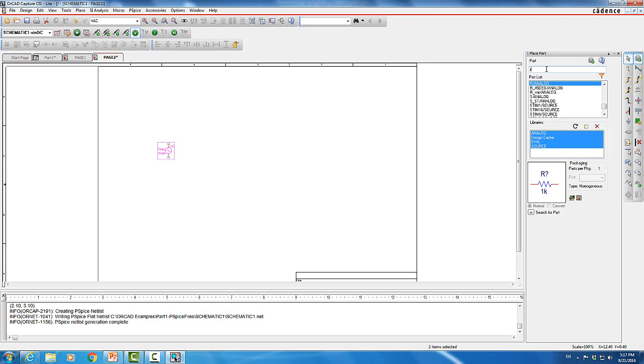So we're gonna apply this voltage source, and then connect a resistor in series with it. So we're gonna say R, and this resistor is gonna be 1K. Then we're gonna have a capacitor C, and I'm gonna press R, which means rotate 3 times. Now we have this capacitor called C1 with a value of 1 nano. To add a capacitor, you come to the search part over here and write C, and right away under the analog library you have C analog. Then you bring it over by double clicking. It comes over here, and then you press R 3 times and place it over here.